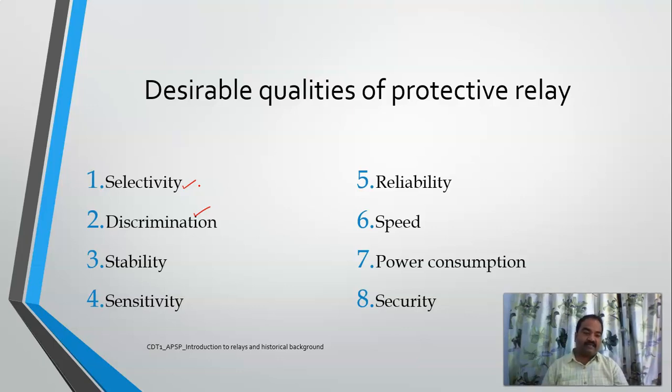Maybe a small rise in current should not be treated as a fault in some cases. So your relay must be able to discriminate whether it is a fault or not. Stability. Your relay must be stable enough. And sensitivity. Sometimes you may require your relay even to sense a very small change in current. So your relay must be ready for sensing even small amounts of abnormality.